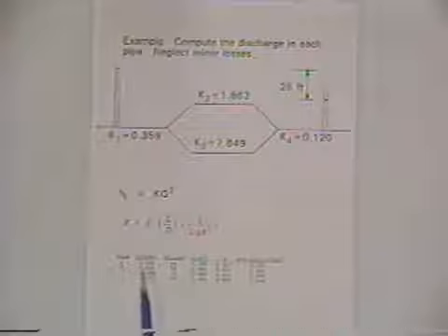And I've set up a little table that converted actual lengths and diameters to K's. And we can do that doing what we've already done before. And so just to use, given the K's now, to illustrate the relationships, the basic relationships we've already covered. It's just applying a little bit of ingenuity to then apply those basic relationships to whatever the problem may require. And so in this problem, we need to compute the discharge in each of the pipes.